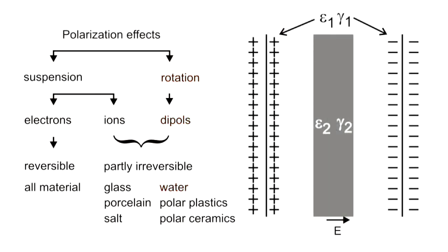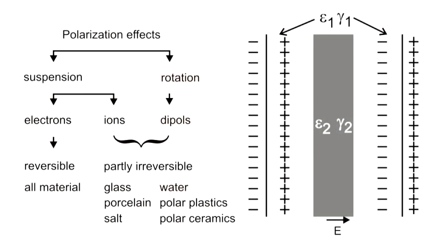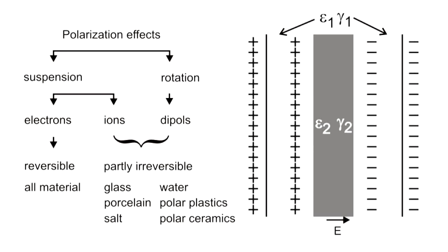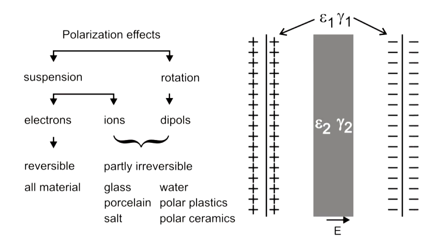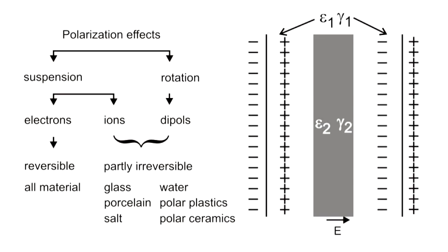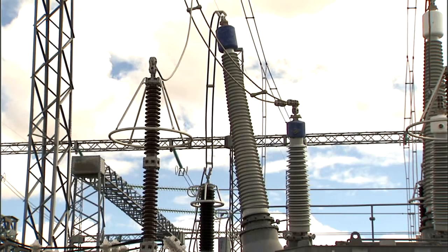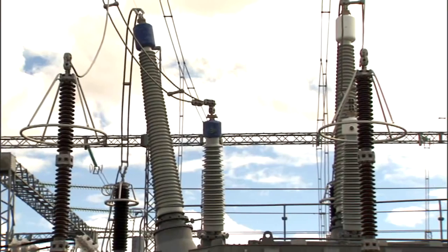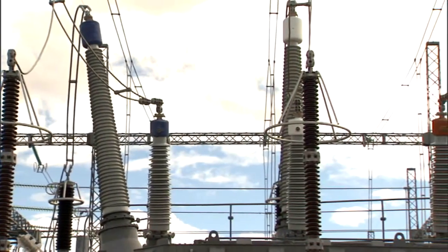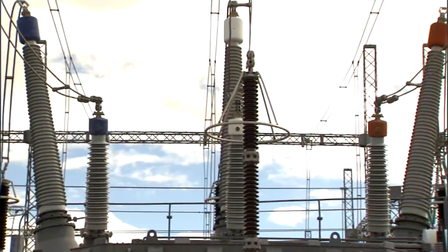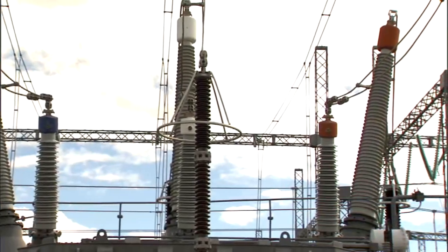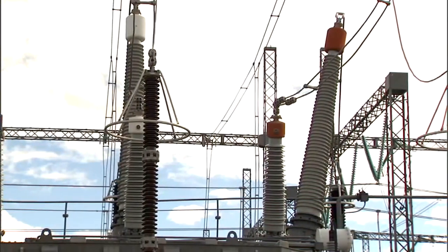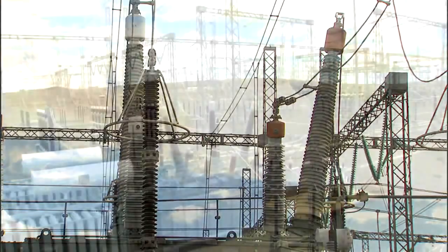The largest share of losses is known as interfacial polarization. Surfaces such as the interface between transformer oil and solid insulation, grain boundaries, or interphase boundaries may be charged with this effect. For bushings, the increasing dissipation factor indicates aging and decomposition of the insulation or the ingress of water. In some cases, badly connected electrodes or conductive control layers can be detected. Particularly on low-voltage bushings, cracks in the insulation and possible partial discharges can also be identified.